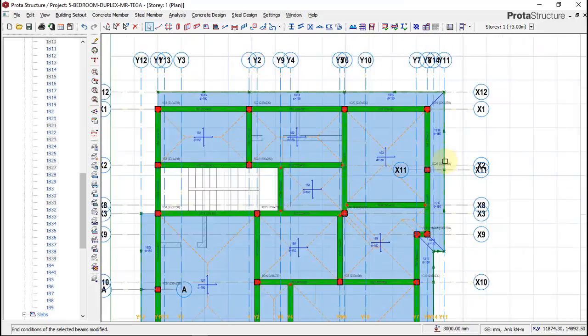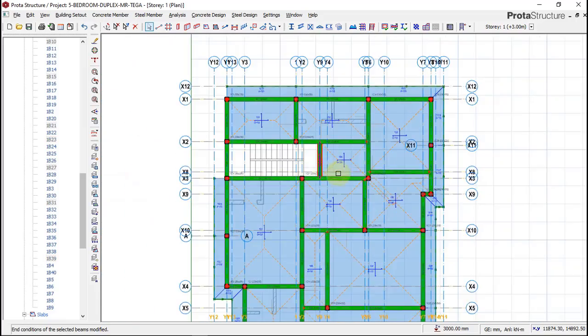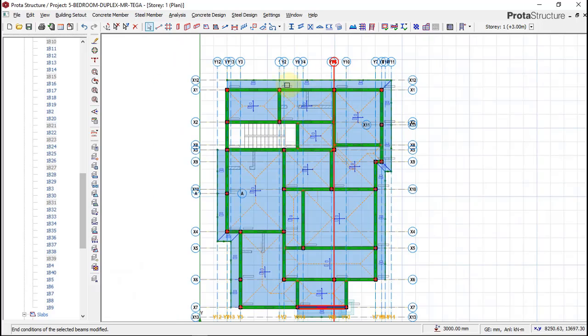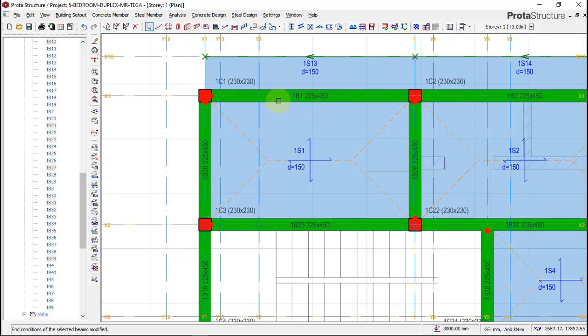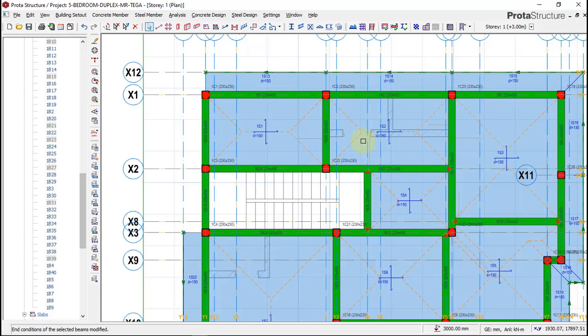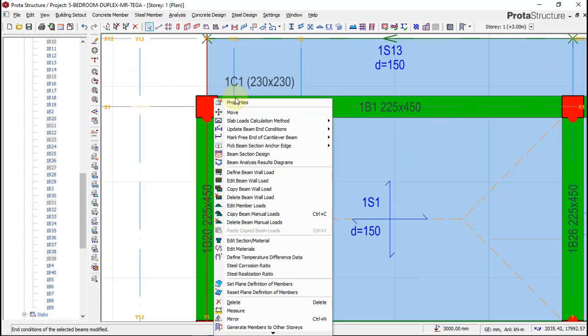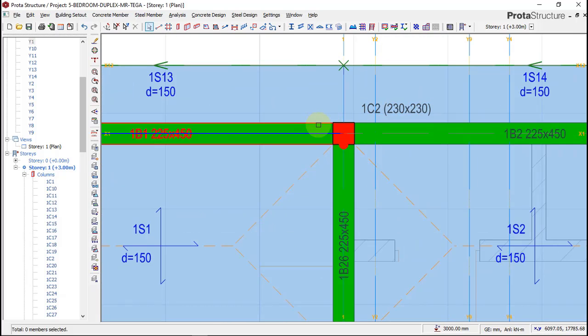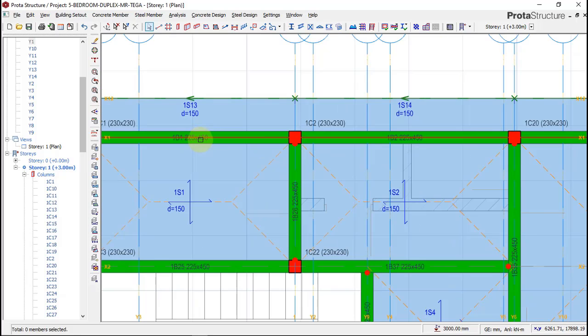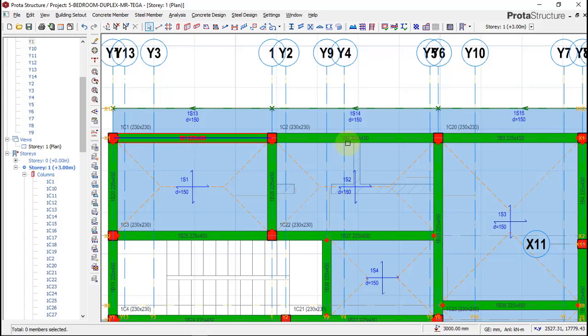Okay, and also in the area of stability. So this is how we apply your beam end condition, your fixed and your hinge end. So this side now, at this area, we have a hinge end at this beam and a hinge end at this beam. But coming to this beam right now, this is a fixed end and this is a fixed end, because it has a continuity.